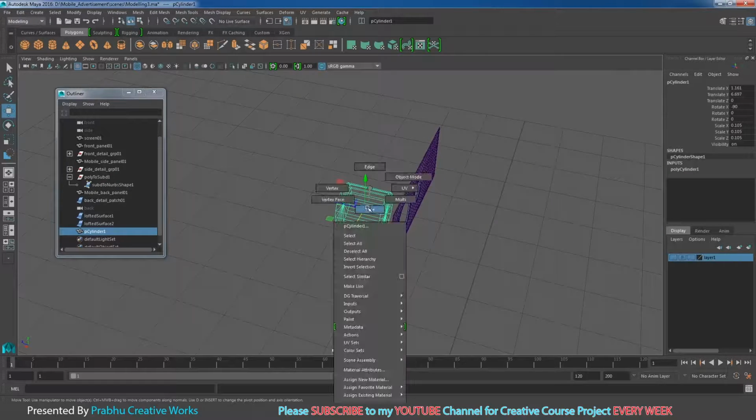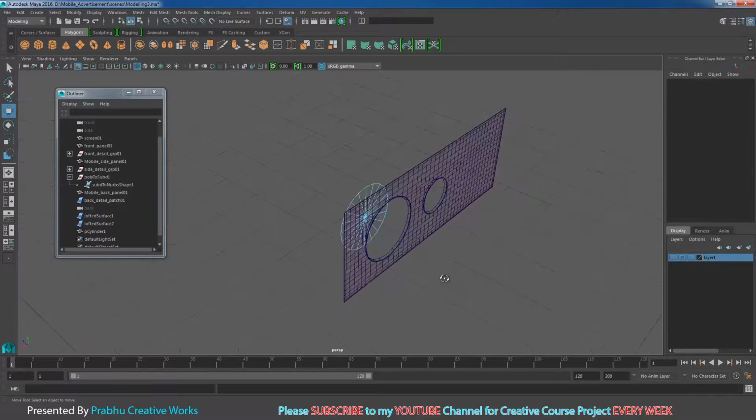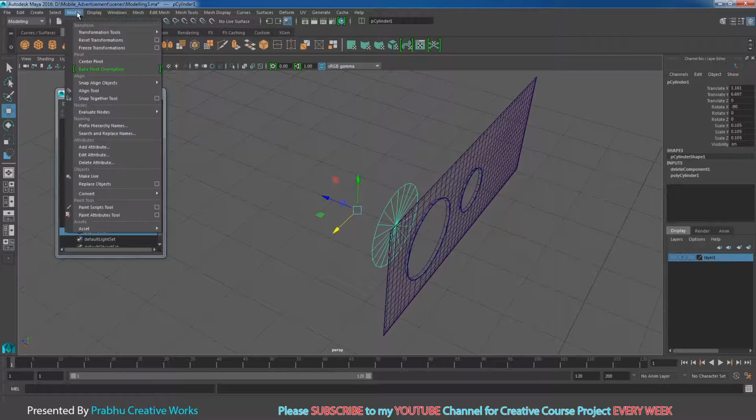Right click and choose this face and press delete. Right click and choose object mode. I want to center this pivot, so with the object selected, go to modify and choose center pivot.